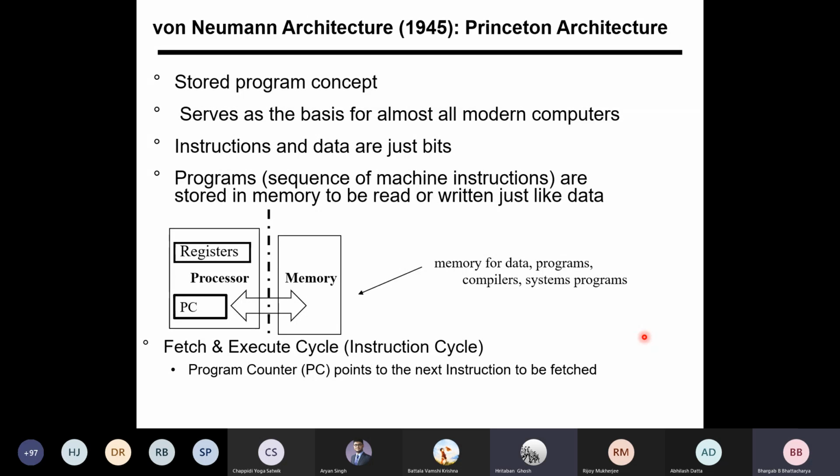Sir, so the instructions can be stored consecutively in memory, like the program counter. Yes, consecutive in memory, yes, possible. Yeah, so the program counter just has to update to the next address, which can be done using a small constant addition to the program counter.